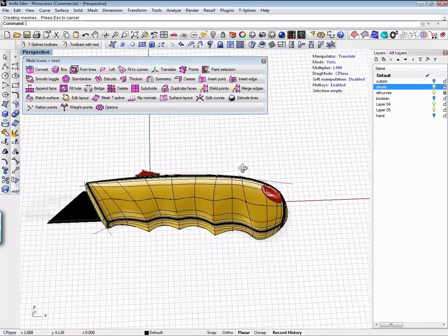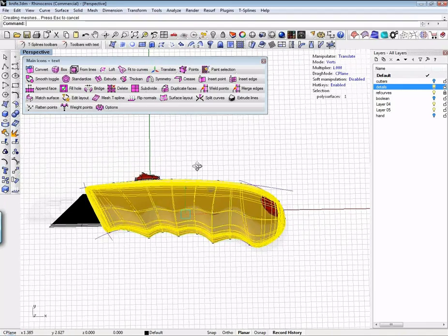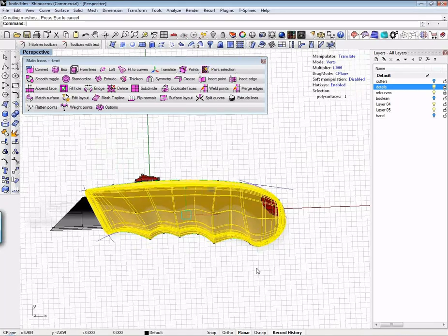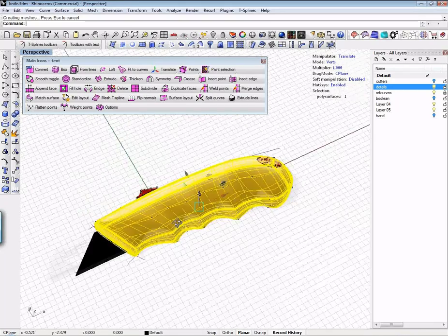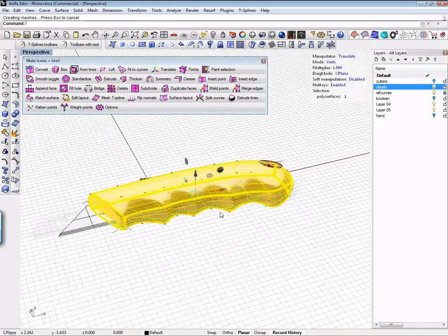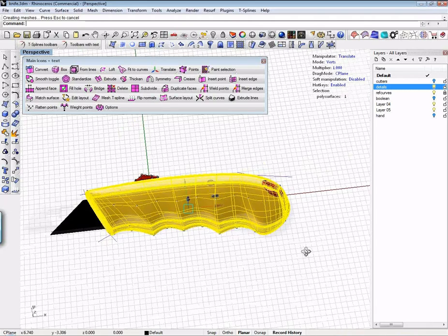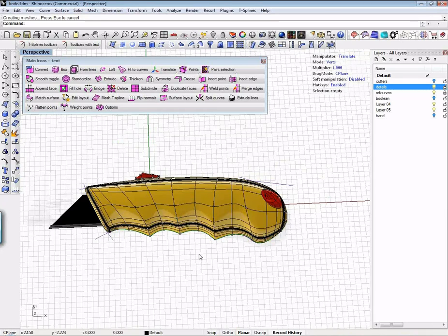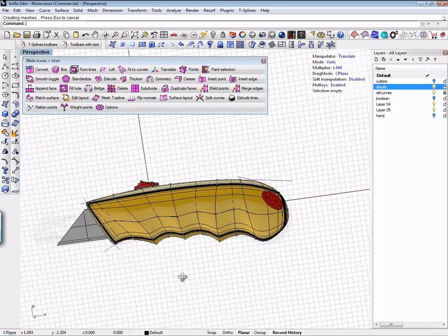This is now NURBS. You're right back into Rhino. This is a typical NURBS poly surface. You can Boolean this, you can trim it, you can cut it, you can do whatever you want with it, and the fidelity on this data continues to amaze me. Every time I've done a T-Splines project and shipped it downstream, it has transferred beautifully into Pro-E, into SolidWorks. It offsets wonderfully. It does all sorts of fantastic stuff.